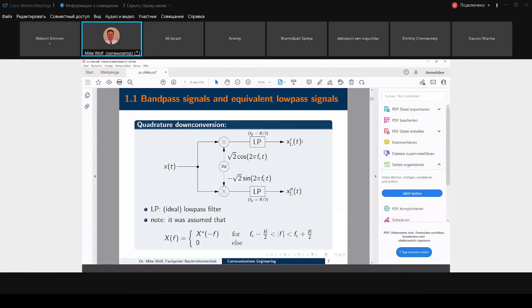If we plug in an analog to digital converter here, and here an analog to digital converter, this is important, then we have just samples. The samples which correspond to this, multiplied with a j, we can then add to the other. If we plug a j to this part, this is only possible in the digital domain, if we just operate with numbers and signal processors. This is down conversion. So the idea is to have data, for instance, in the low pass range, low frequencies. We can use digital generation of these signals.